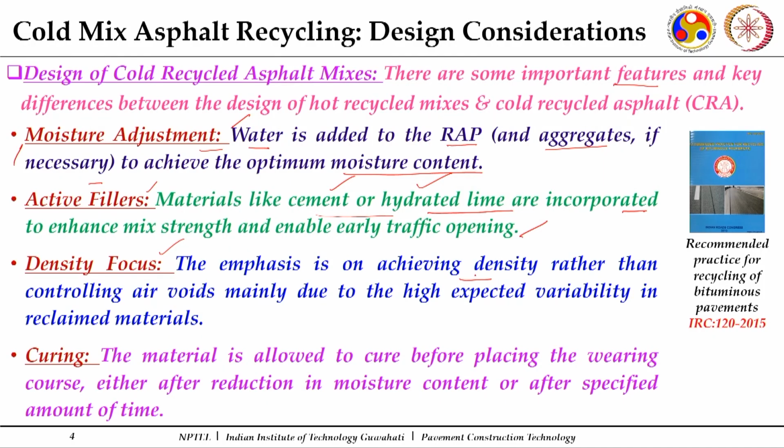But here you will find more concentration is given specifically on the density, because we are producing it as a stabilized base course. So more focus will be on density compared to the air void content, because air void content may show a high variability with the change in your reclaimed materials, because you are involving a greater depth of layers in it.